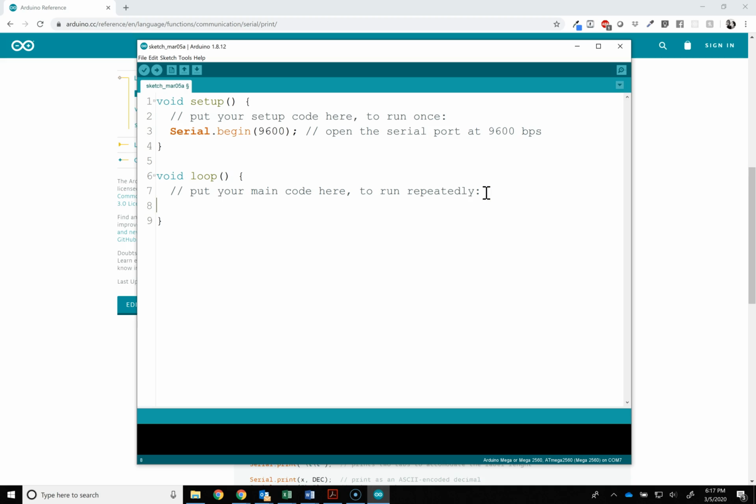And so inside our loop, I'm going to put my spaces so I can have consistent formatting here. What I need to do is call that Serial.print function. So Serial, and you'll see as I complete the word, it turns red, lets me know that maybe this is a legit function. And I'm going to call print. Print is my function. And what do I want to print? Let's keep it classic, and I'll go Hello World, right? Hello World. So that's it.